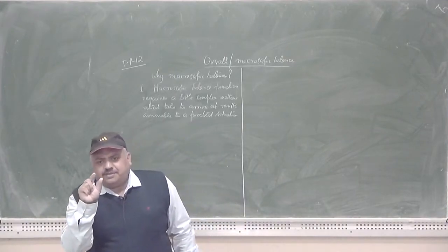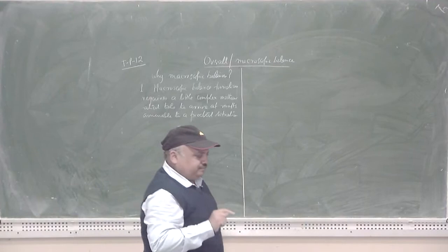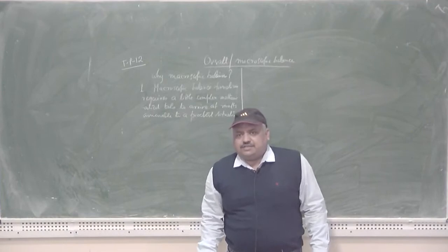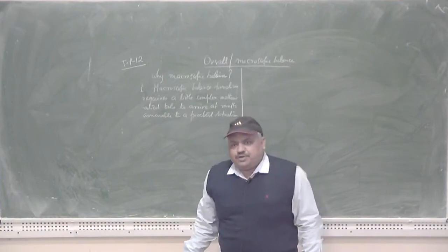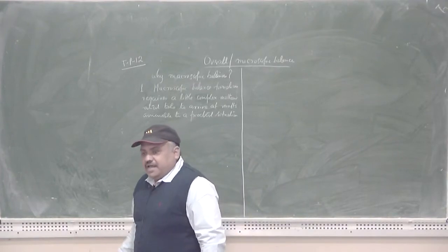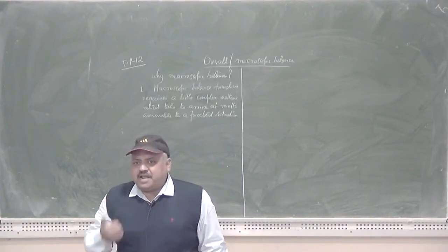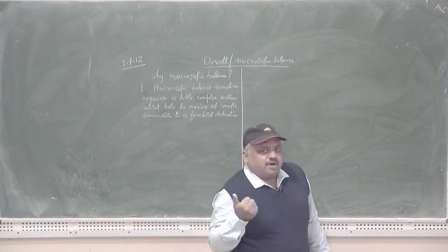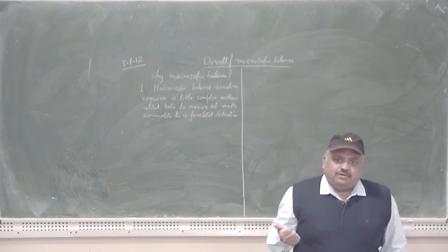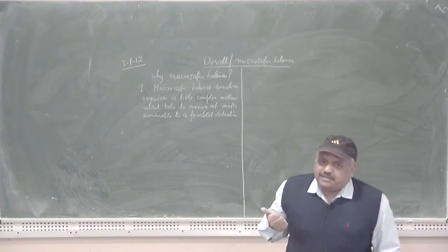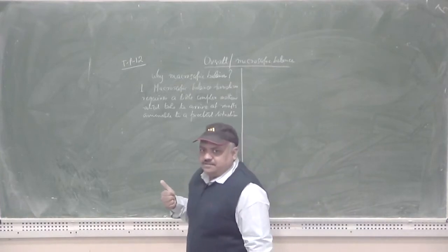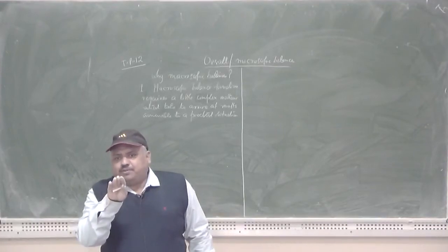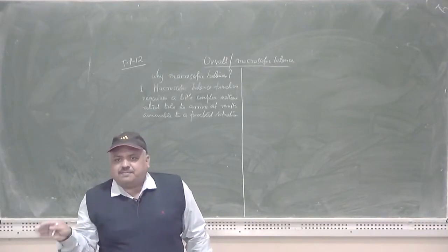Knowing the dimension of the slag nozzle or slag notch, if you start applying the differential balances in those cases, so it is very cumbersome to take a fluid element as the slag is flowing at a higher temperature from the blast furnace to the atmosphere. So it creates a very cumbersome situation for a practicing engineer to execute. However, by adopting the common principle of the macroscopic or overall balances, it is possible to arrive at the time required for the complete cleaning of the slag from the blast furnace.